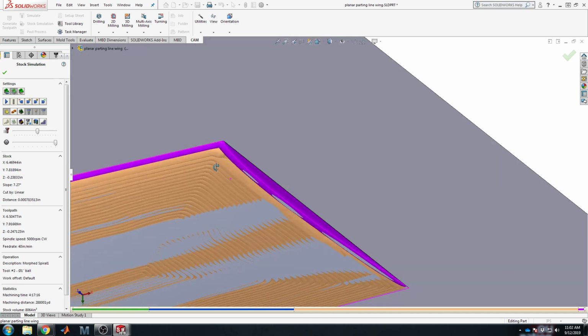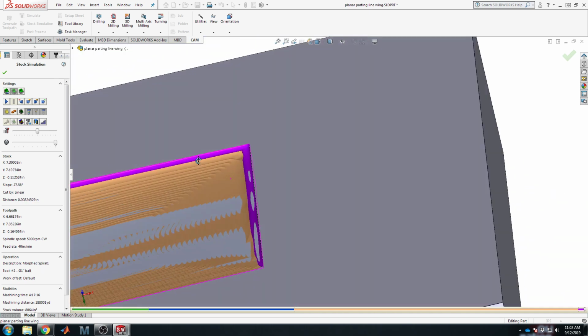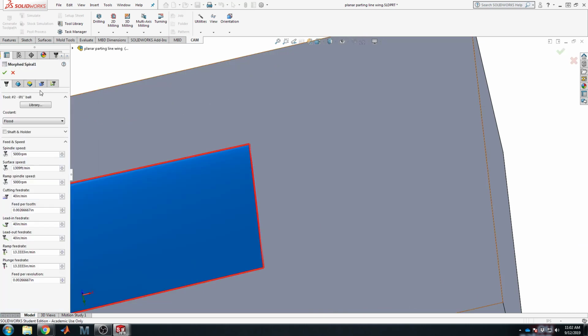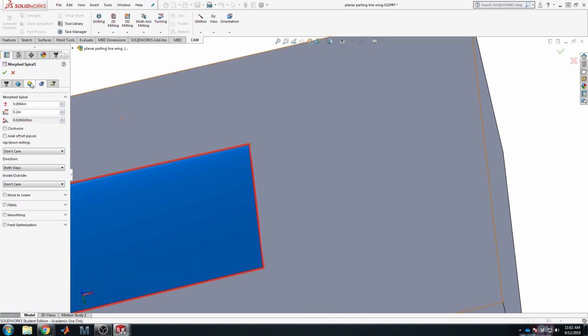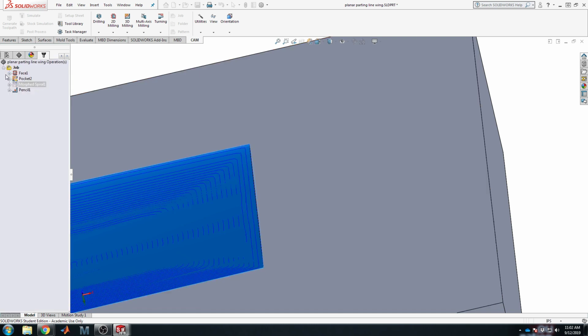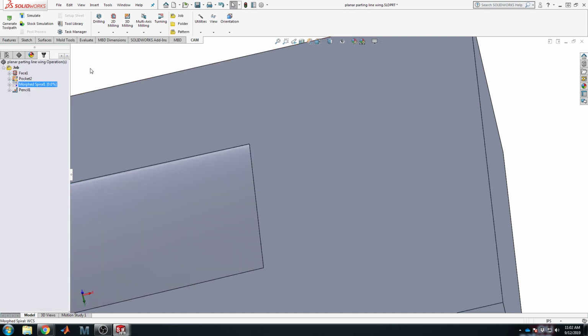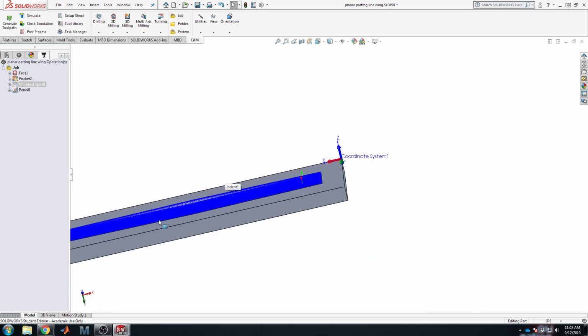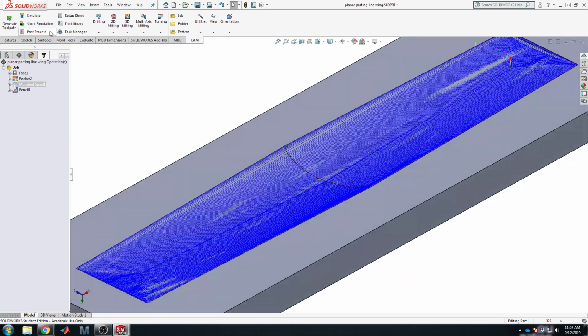But a lot of this surface cleanliness is a lot better. If you really wanted to eliminate all reasonable sanding tasks, if you wanted the machine to do all the cutting instead of people, you could take this down and get something in like the 5,000ths, 3,000ths range. And then the scallop height is so incredibly small, you don't have to bother with hand sanding anything. It's especially useful on aluminum molds because hand sanding aluminum, while possible, isn't fun.